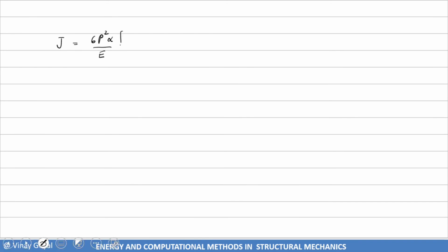So I only have the integral from 0 to L of x squared over A of x squared dx, minus lambda, and I have the integral from 0 to L of A of x dx minus V naught. Why? Because this integral gives me volume, and I'm keeping the volume constant. I don't know what A of x is, which is my goal of finding, and that will minimize the deflection somehow.